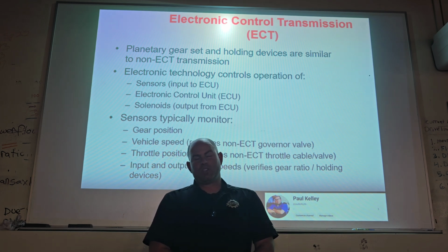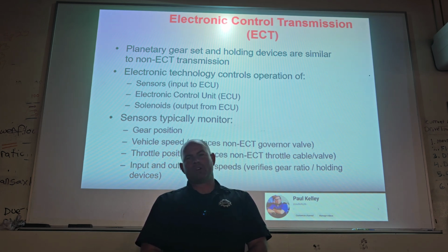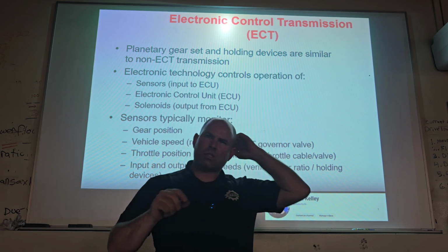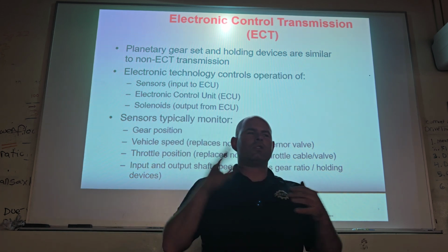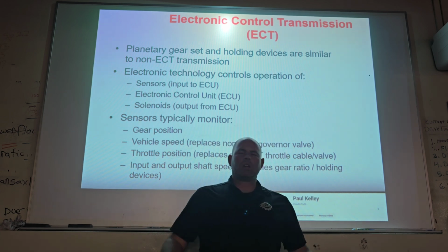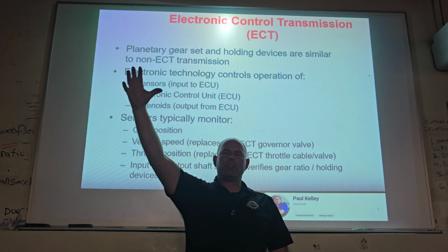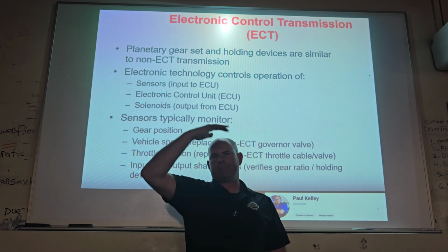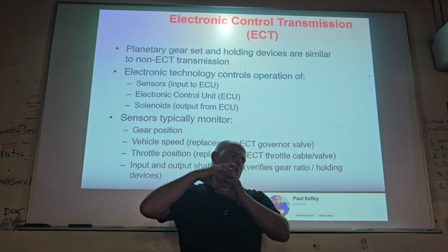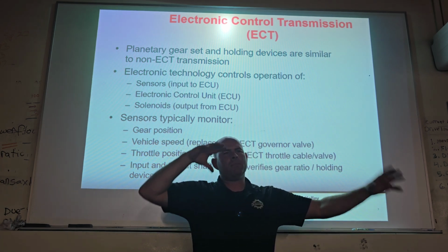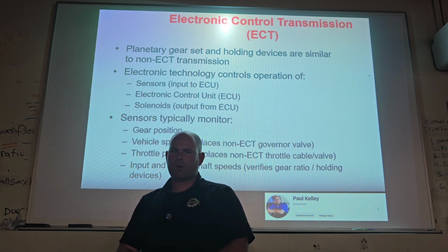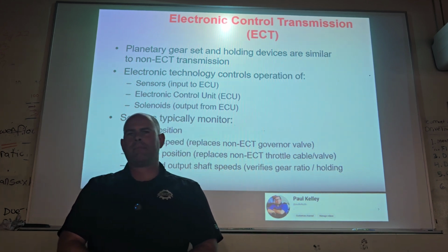Do a software update, you do an ECU reprogram. You'd literally plug into it. Maybe you'd look for TSBs and it would say, customer's complaint is the shifts occur too late. You'd look up, boom, you got it. It would say, hook up scan tool, download the software program from TIS or whatever. That'll go on your computer. Your computer will overwrite the existing program, and bingo, that problem is solved. It was literally solved by software. We do fix cars like that.